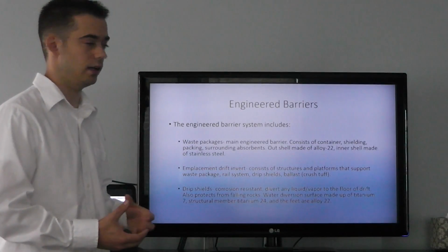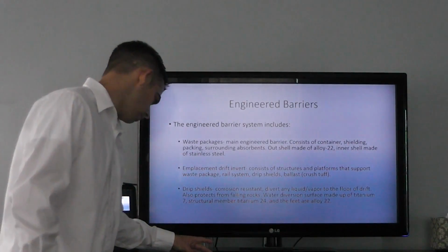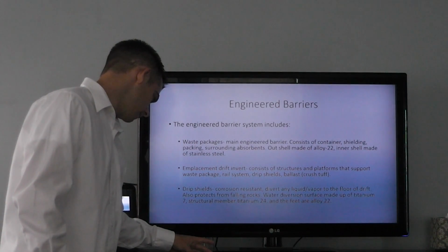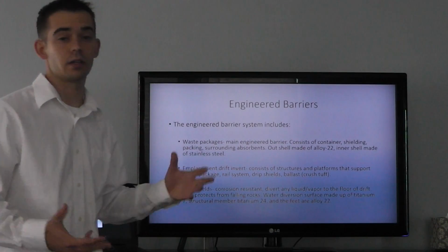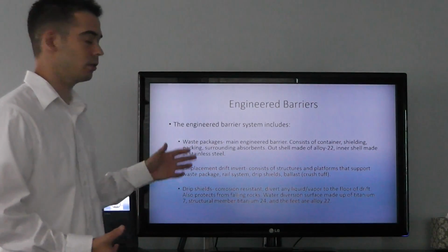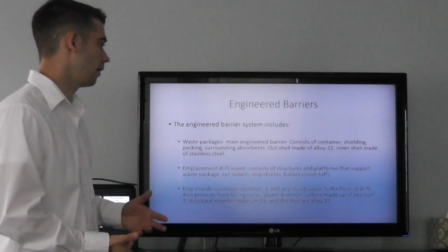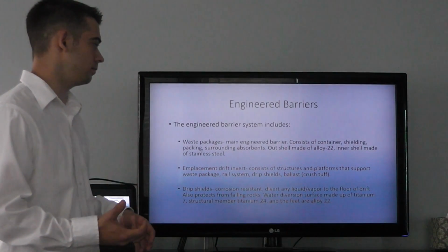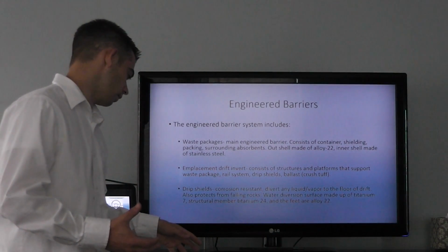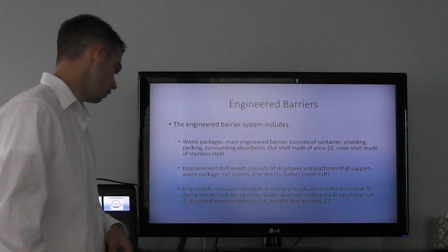This puts a compressive stress on it instead of a tensile stress, which is supposed to minimize the eventual cracking of these welds.